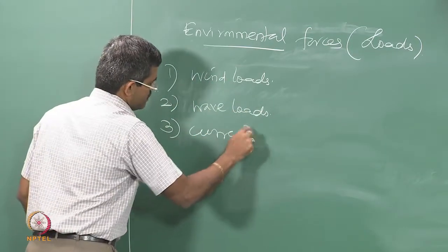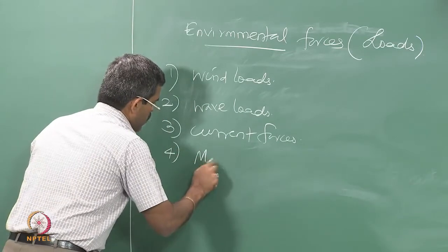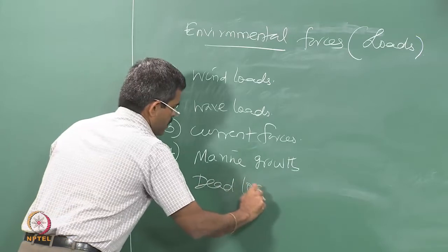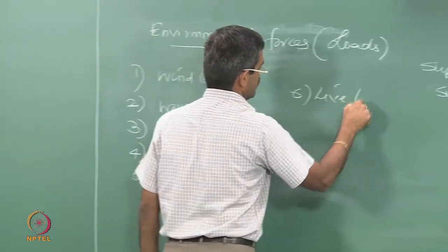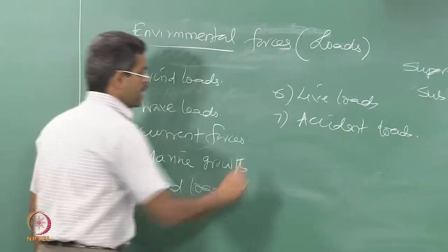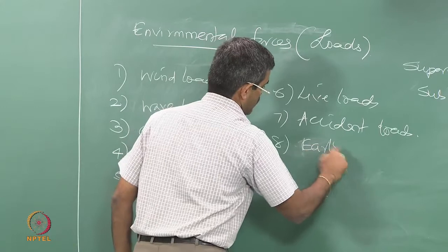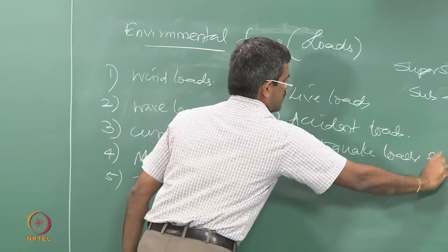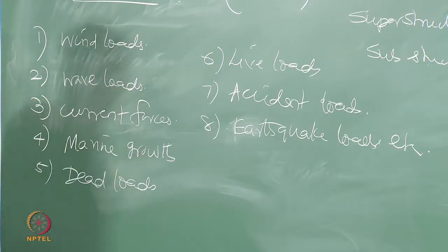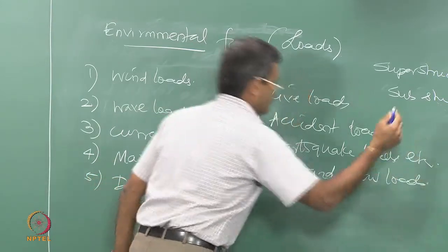Waves also will have current action, they will also have marine growth, there can be dead loads, there can be live loads, there can be accident loads which is called collision loads, there can be seismic forces, let us put it as earthquake forces, etc. We have anyway discussed all these things with the respective equations, with the respective spectrum, ice loads, acting on offshore structures.